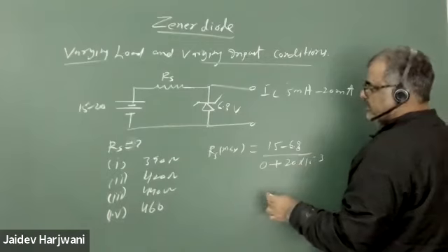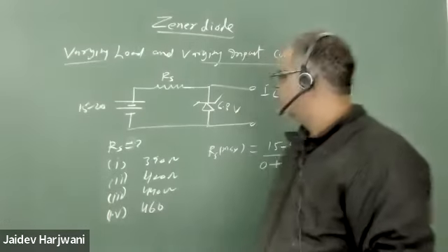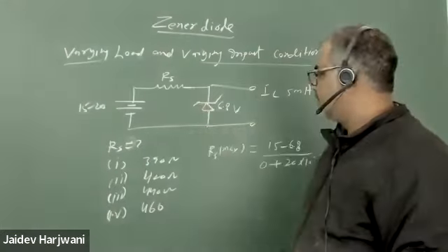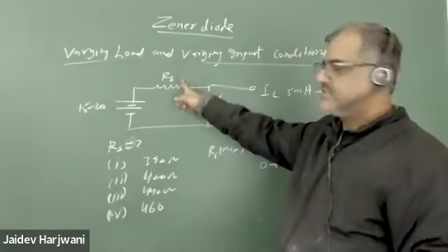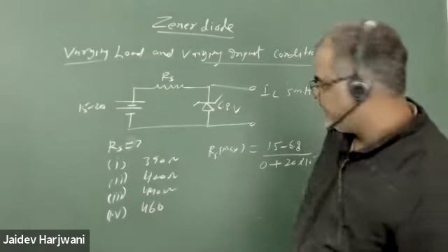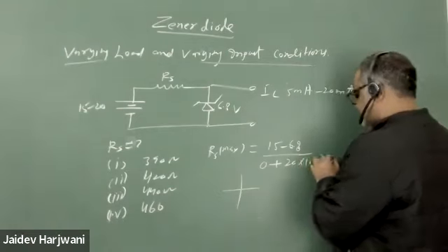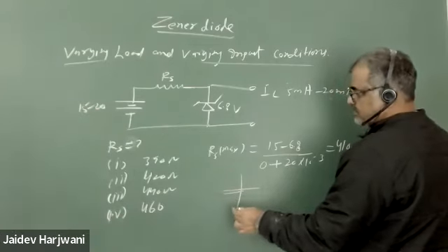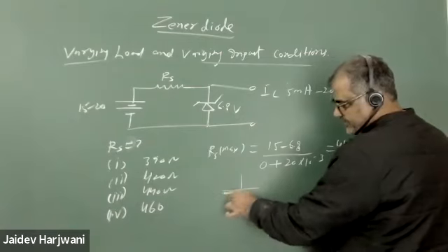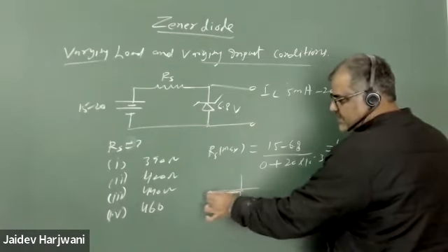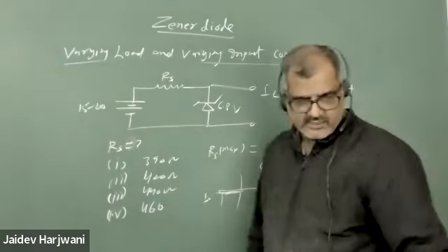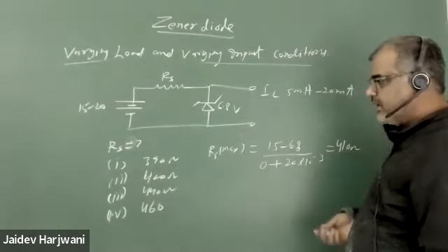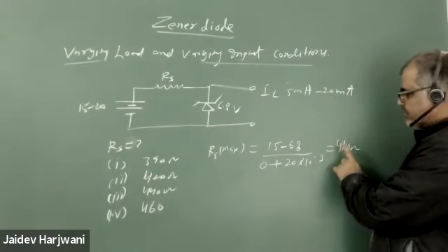Sir, the load current is given and the voltage will be 6.8 there. The resistance is not known yet, so you can take it, and 410 is coming. Very good, 410 ohm is coming. This current is saturation, so I told you IZ sometime you can assume 0. That will change nothing, it will only make this limit upper. So now this is 410 ohm, so your resistance should be below this one.